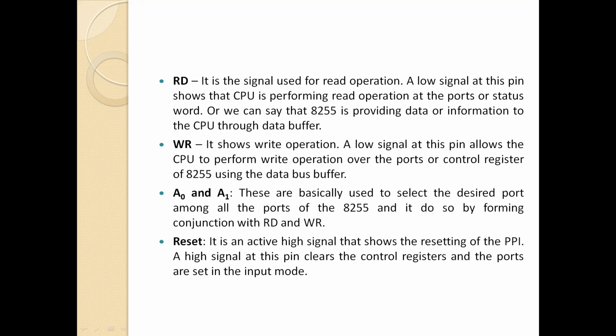Further, there are the A0 and A1 pins. These are basically used to select the desired port among all the ports of the 8255, and they do so in conjunction with the read, write, reset and chip select pins given in the read and write control logic block. Reset pin: it is an active high signal pin that shows the resetting of the PPI. A high signal on this pin clears the control registers and the ports are set in the input mode.